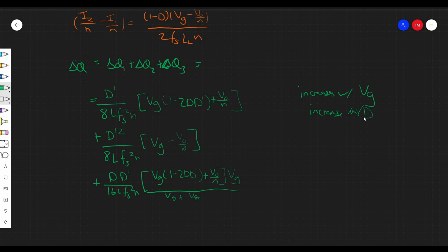So we're going to choose the max D and the max Vg again: 48 volts and D equals 0.4. We're still going to choose that our maximum power transfer occurs for some maximum D, which is slightly less than 0.5. We might also choose N at the midpoint of Vg. So maybe N equals V out over Vg when Vg is, say, 36 volts, right in the middle. That way, over the full operating range, the current peaks don't get too high. Maybe that would be a choice you would make.